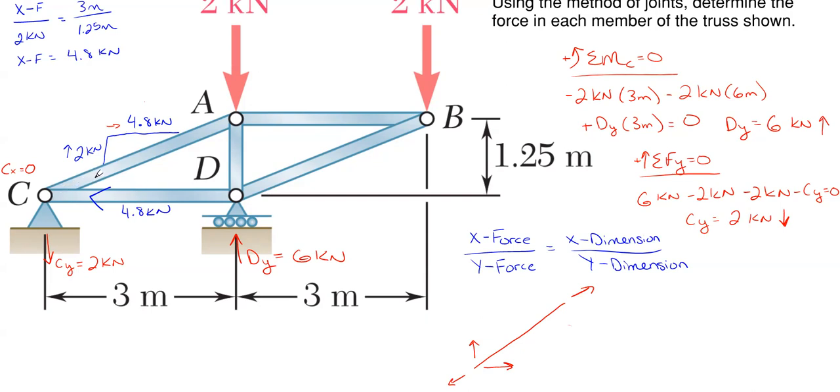Okay, so we have all our forces on joint C. We just have to complete a few arrows here. So as I said, we are up and to the right relative to joint C. So my arrow can either be down and to the left or up and to the right here relative to joint C. Well, dictating which way my forces are going here, it has to be up and to the right at joint C. Okay, so we have C completely solved for our equilibrium here and our arrow directions.